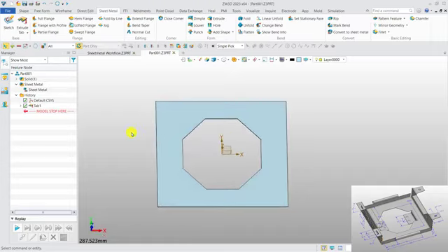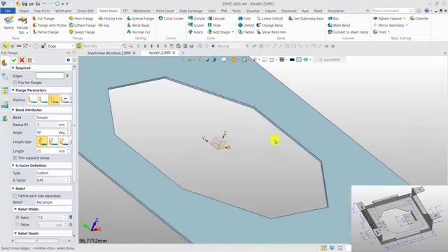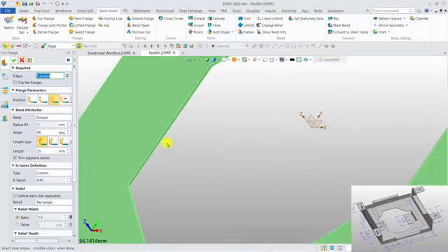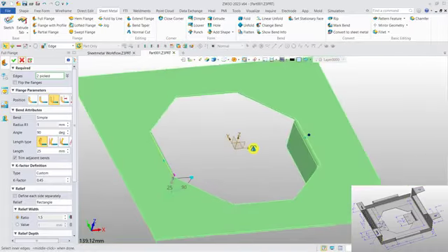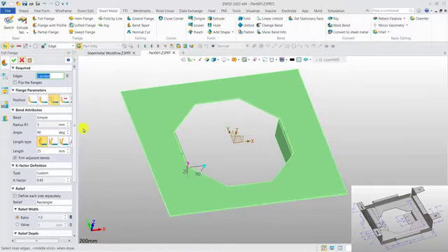And then next we create a full flange to the edge of the rectangle. Okay, and we select the edge one and the other one. Okay, and for this flange, we can use the S bend.